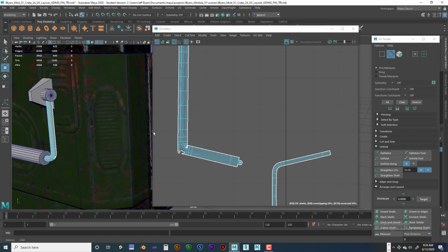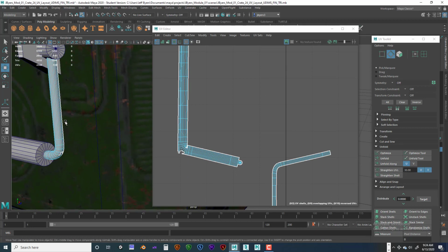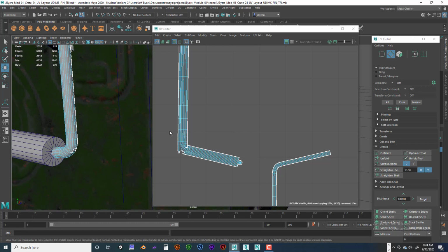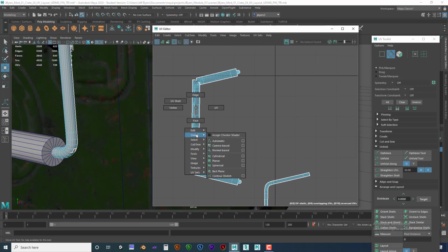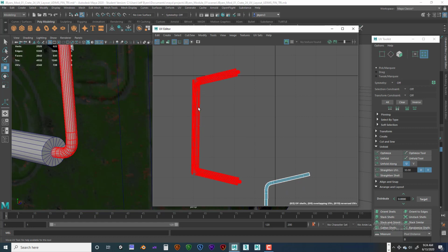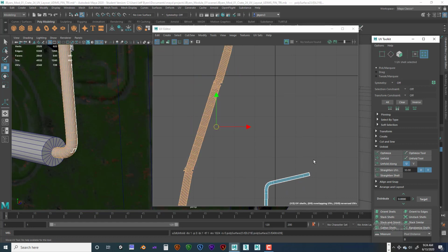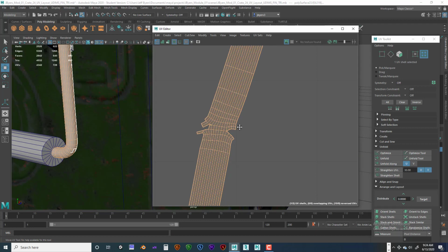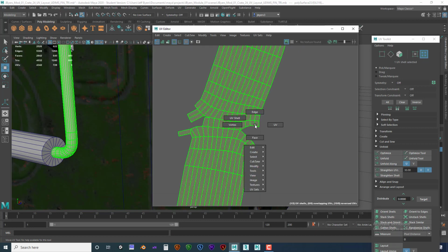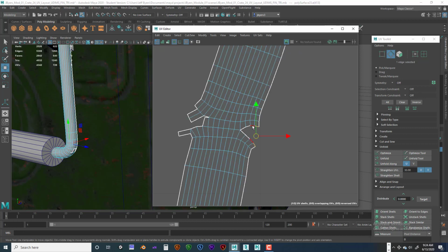You got some janky stuff going on here, and you've got some overlapping UVs right there. If I click on that to shell, and I click on unfold, that does help. We got some destruction right here, right? But we could go in here and click on that edge, right? And go ahead and sew that. That could help a little bit, move and sew.